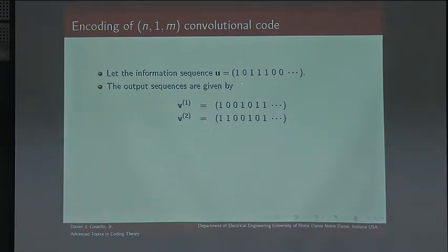And the same thing here. We just add the last 3 bits: the current input bit and the 2 past gives us 1 here. Current input bit and the 2 past gives us 1 here. Here we get the current input and the 2 past, so we got even parity here, so it gives us 0, etc. So that's just walking through the discrete time convolution. And again, we can say this is the output, this is the code word, these 2 sequences. But if we want to put them together into one sequence, we could take the 2 bits at time unit 0 and the 2 bits at time unit 1, and write it all as one sequence like that.